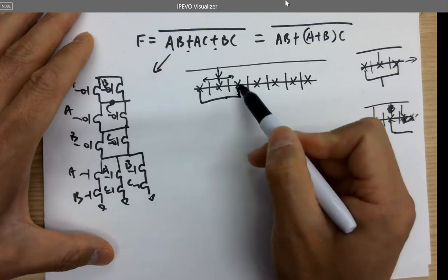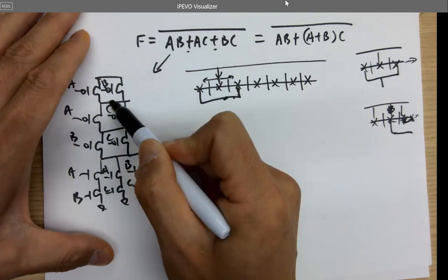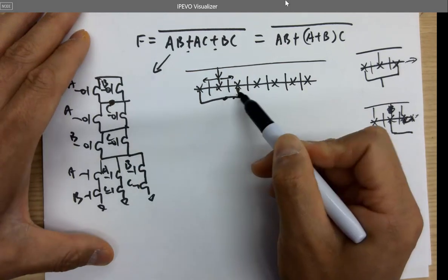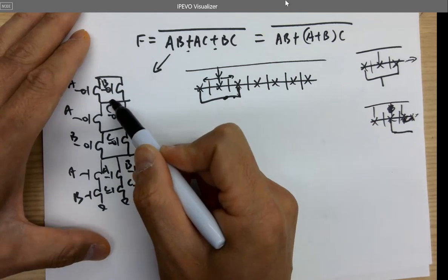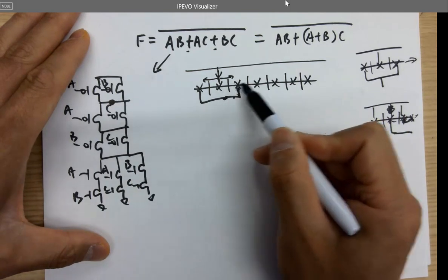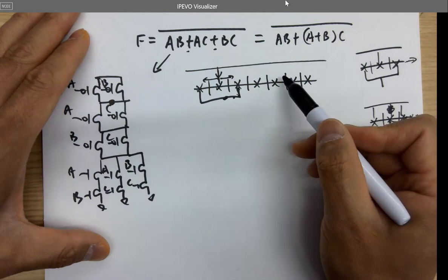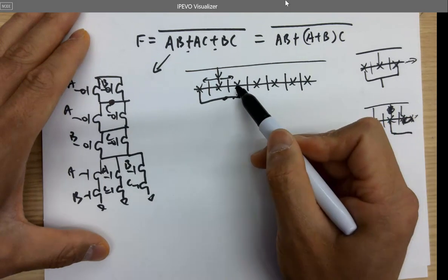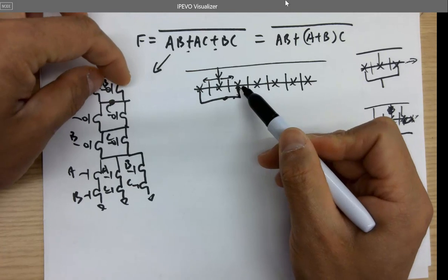It's just one wire, it's one node, right? So this node is this node. And this is connected to the drain, the sources of the two PMOSs over here, already in the line, since I just drew a one line to make it easy to lay out. That's why we want to utilize this one and use it as the output of the first two PMOS transistors.